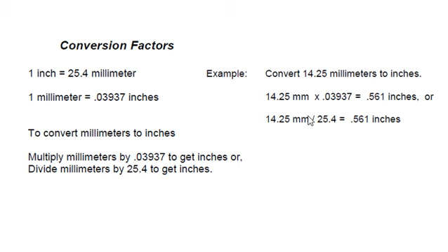So here is your example. You're going to convert 14.25 millimeters to inches. Write down the millimeters you're given, and then you divide it by 25.4 and you get this. Just try to remember one of them. 25.4 is easier to remember than this, so that's up to you.